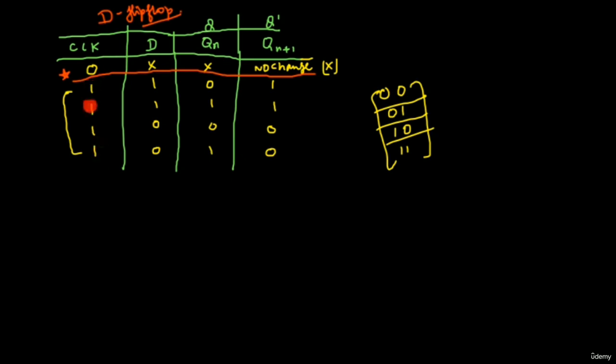Okay, now let's study this one. For every one of the next cases, the clock is active, so we are not going to focus on the clock anymore because it remains active. Now, let's start with the 0 0 case. That should technically be the first one, but I twisted it a little. So 0 0 means the D is 0, the input is 0, so the output is 0, and the next state is also 0. As we are using NAND gates, it is going to be 0. We will also see that in diagrammatic form, but for now it's just a 0.